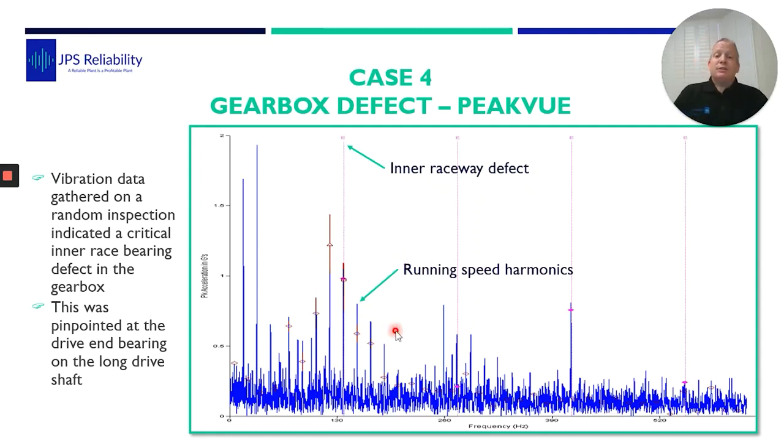So I was quite impressed that an inner race defect in this gearbox has energy so high that it transfers from the rolling element to the outer race, to the casing, the outside of the gearbox, which itself is shaking at over 100 millimeters per second, and we pick up the transducer, and we even pick up the modulation as the inner race defect is coming close to and away from the bearing.